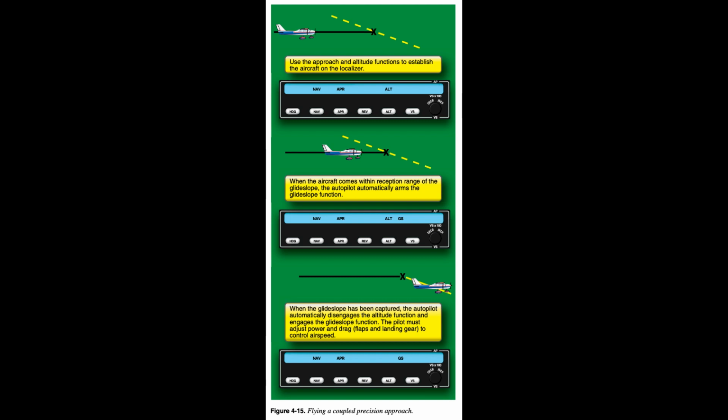This process is transparent to the pilot. Most VNAV functions do not qualify as approach vertical functions, and many FMS/GPS units inhibit that function during approaches.